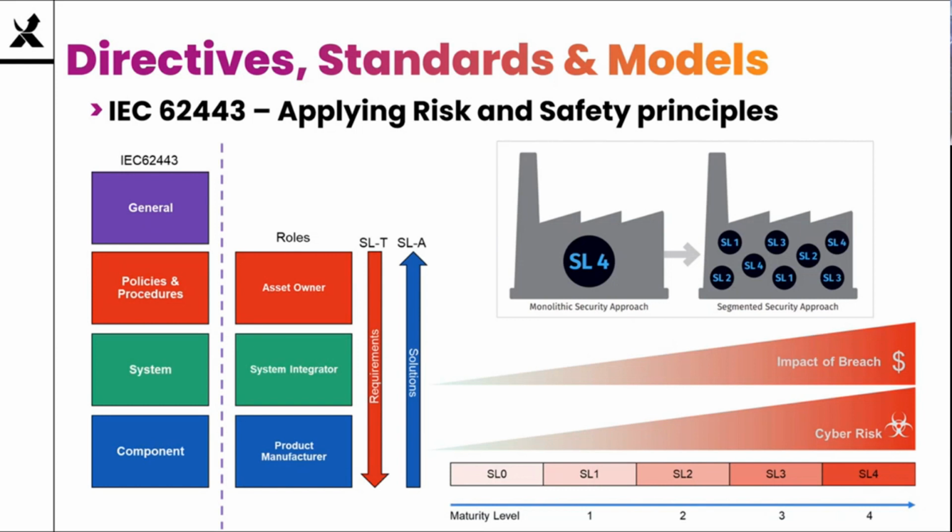Well, the answer to these questions is somewhat surprising. According to the current IEC 62443 standards, there is no relationship between maturity level and security level. So you could develop and maintain a security level 4 system using a maturity level 1 process. However, it would stand to reason that the security level achieved may not measure up due to the lack of repeatable processes. For this reason, it is recommended that asset owners actively practice continuous improvement and achieve maturity levels more commensurate with the SL-Ts that are defined.